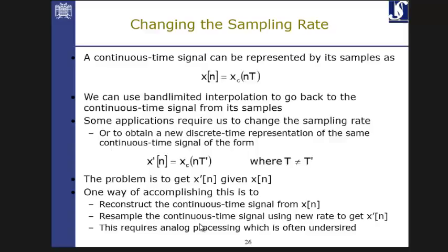For example, you do the downsampling with a factor of 2, which is shown by x2 of n. It means taking the initial sample to be preserved, then every other sample is cancelled from the next one. So this one, you ignore. This one, you take, but you put it back here. So the next sample right afterwards is this one. Then you ignore this sample, and you take this one.